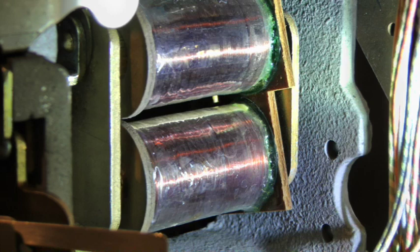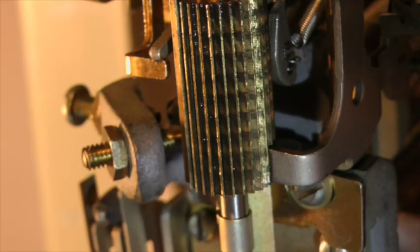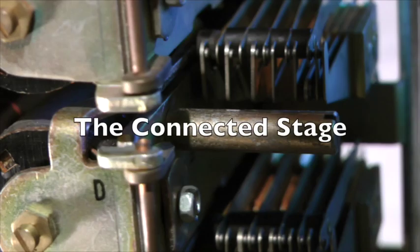The released E relay de-energizes the rotary magnet, which releases the rotary armature. This disengages the rotary pawl from the rotary ratchet. And the rotary interrupter lever releases, returning the interrupter springs to their normal released position. The line finder is now in its connected stage.